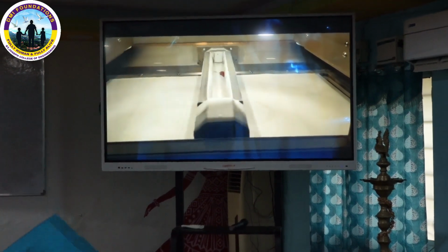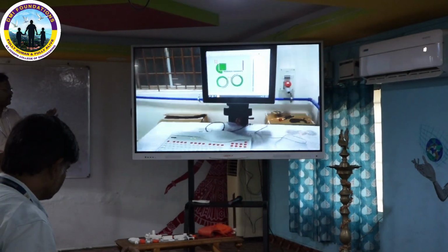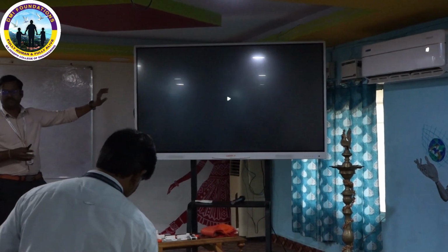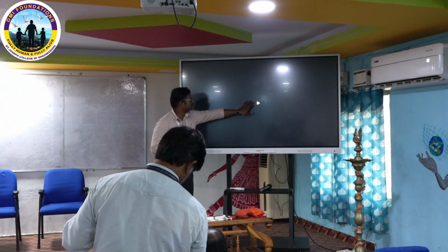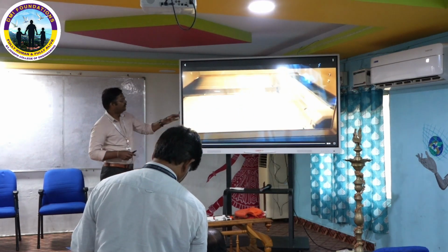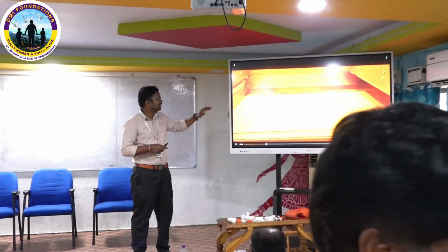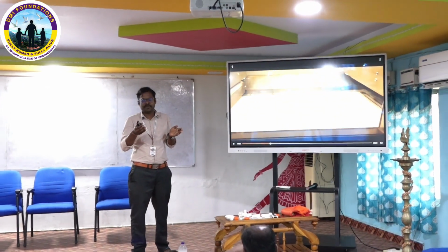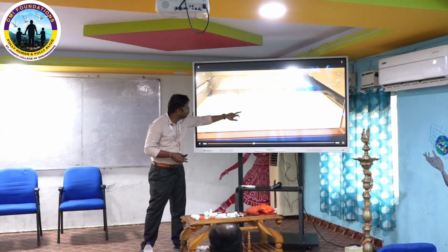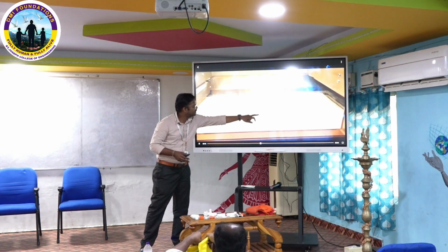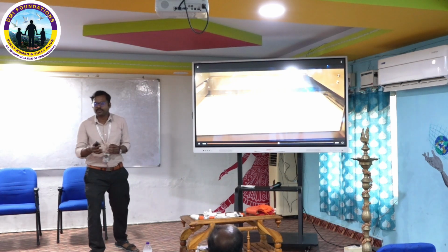Okay, you can't recognize much of this, but I will explain. First, this is the cross section which is going to be sintered in the layer. First of all, this is the recoater which spreads the powder on the previous layer. Then a little warm-up happens. Then the laser, which is not visible to us, sinters that portion. You can now see the black-colored cross section. It is sintering the powder.